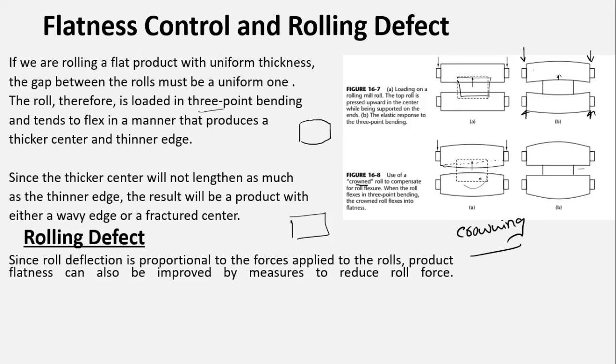The other way is that because this defect arises not only from this 3-point bending but also due to the high roll forces, we should find the way out while designing the rolling operation. We should focus on ways to reduce the roll force. When we perform some numerical analysis or look into some problems of the rolling operation, we will see how we can reduce the roll force while designing the rolling operation.